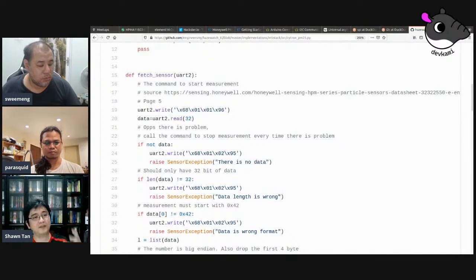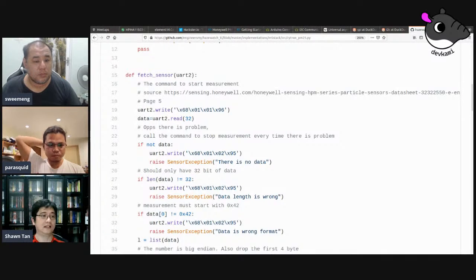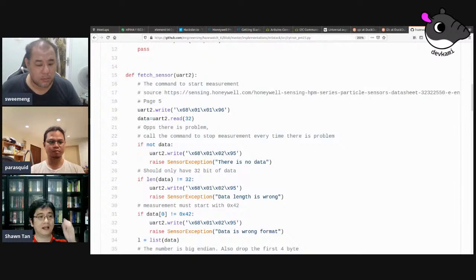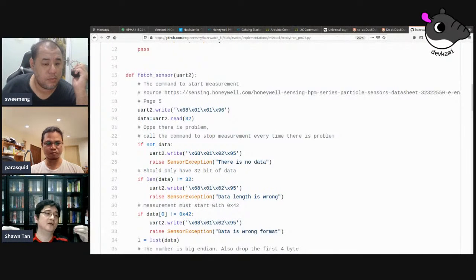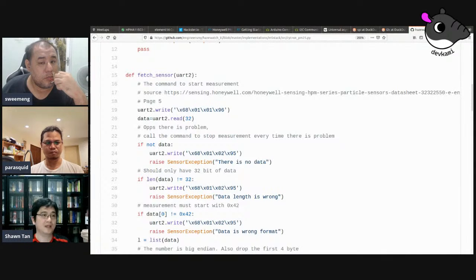So they have clock information transmitted together with the data. Whereas for UART, there is no clock being transmitted on the line. The data is just sent on the line, hence the word asynchronous. So this requires that both sides, the receiver and transmitter, be pre-configured to run at the same speed. That is the requirement.